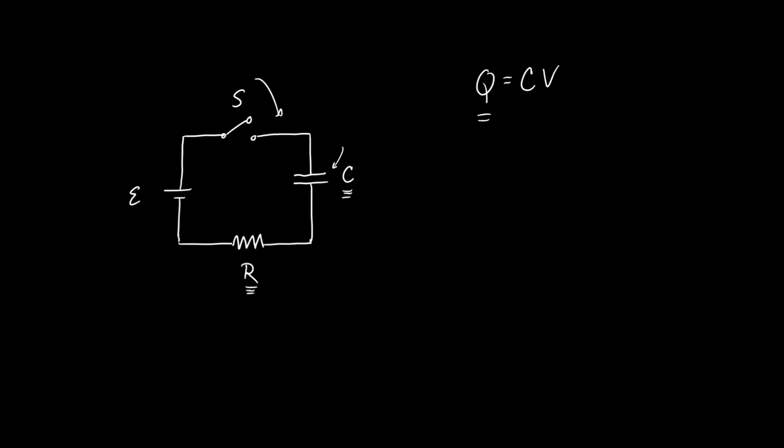So when I close this switch and wait a long time, eventually my capacitor will come up to full charge. A long time in circuit parlance can be milliseconds. I want you to be really aware that a long time doesn't necessarily mean what you think of as a long time. In fact, we'll show how long it takes for most circuits to come up to their full operating position, and it's very short. It doesn't take long at all. We might make a few that purposely take a long time, and by long time I mean 3 or 4 seconds, but a long time in circuit discussions is not long.